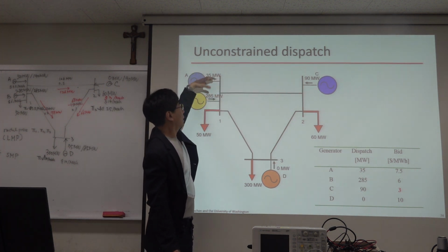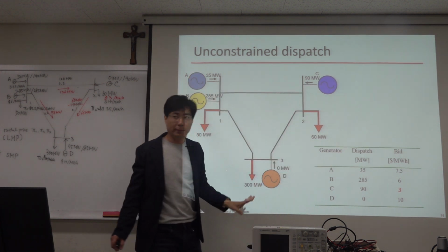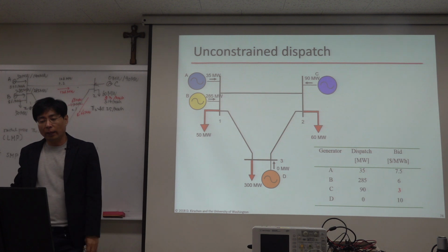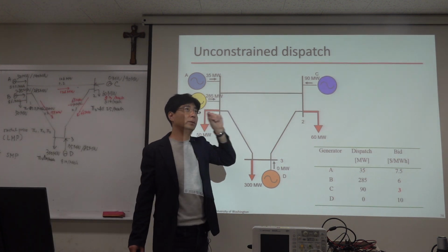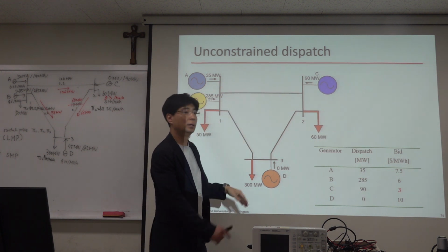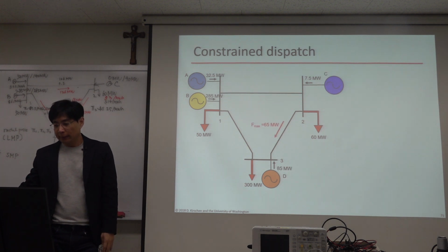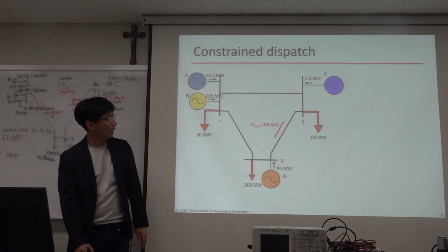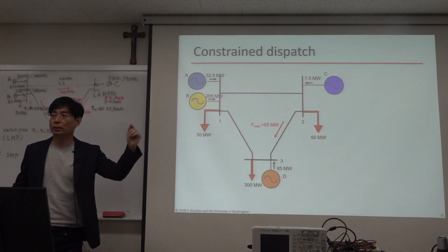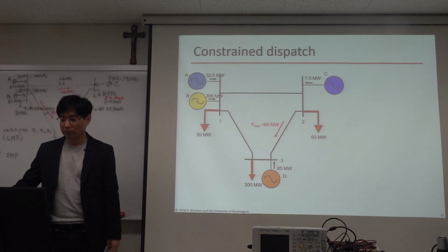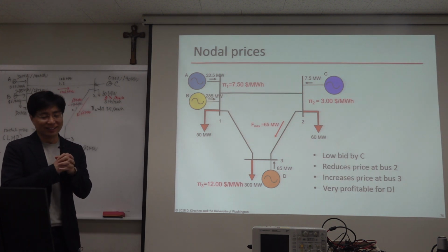So it can be plus or it can be minus. And describe the power flows using delta P1, delta P2, delta P3 here, here, here. Check they satisfy the constraints. And delta P1 plus delta P2 plus delta P3 is 0, right?